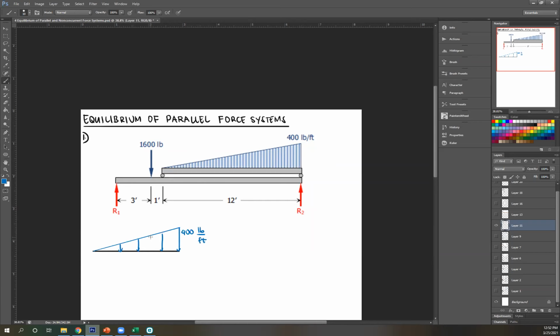So this means a roller. And for a roller, the only reaction it can give is vertical reactions, because it cannot prevent horizontal motion. So for a roller, it's only vertical. Now for a pin, which you'll see later on, looks something like this. This one has vertical and horizontal reactions. So roller, only vertical, pin, horizontal and vertical. So we both have rollers, so there's only vertical reactions for each. Let's call that your RA. Let's call that your RB.